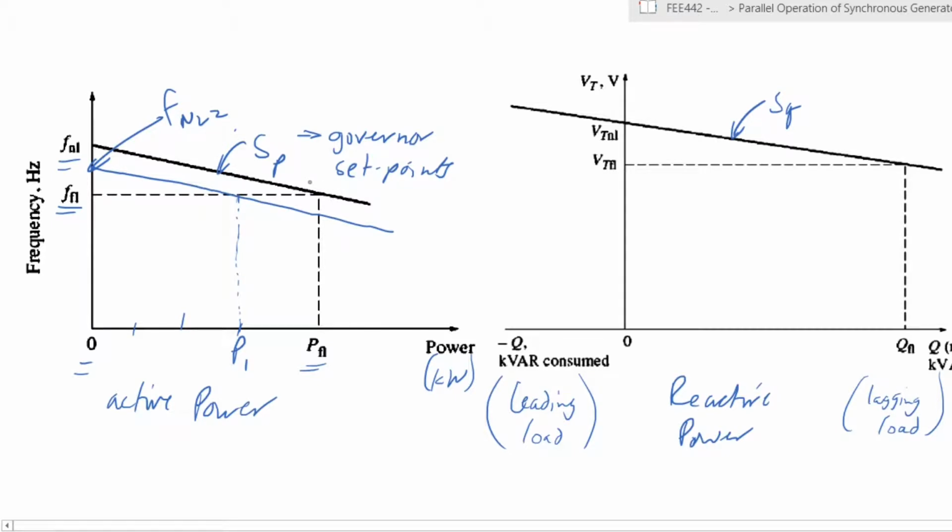That is why if you stand next to a generator when it is first switched on and a load is applied, you will hear the frequency of the sound dropping. It is an actual change because the governor is doing its job of changing the position of the frequency to match the load being supplied. However, if you have longer term load requirements, that's when you can change the actual governor set points.